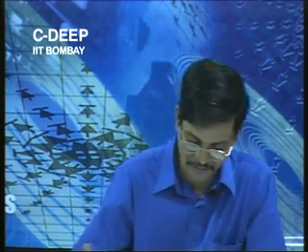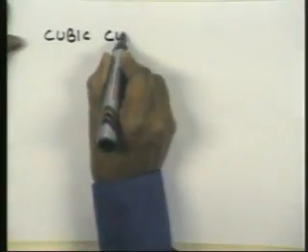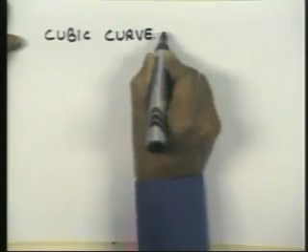This can be generalized, as I said. If you have prescribed accelerations, you can fit a higher degree polynomial, differentiate it for velocities, differentiate it for accelerations, and make the profile match the conditions prescribed at I and j. Okay. So, if you look at the cubic curve fit that we just now achieved,